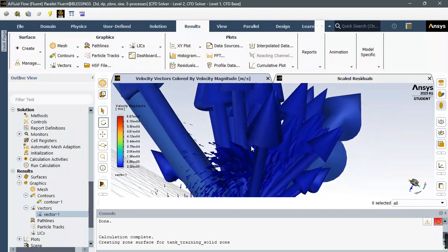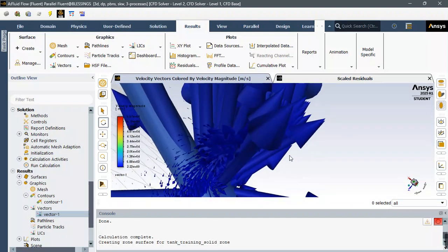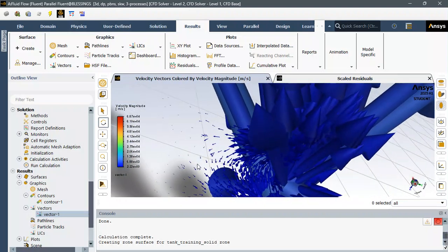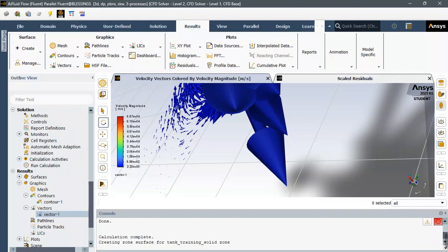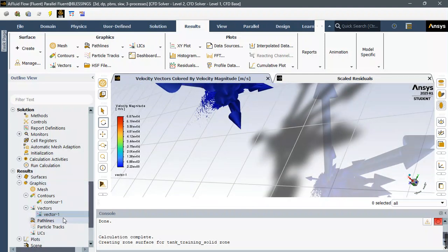You see how they are moving, so you can tell, okay, the particles are moving this way, meaning they will hit the wall. Where we are having a circular motion here, you advise your team to say, okay, if we pick this injector, we'll have particles moving in this fashion. So make sure you know how to consider the walls. For example, at the walls you have higher velocities circulating, moving in a circular pattern. All that has to give you some meaning to say, oh, here we have the highest concentration of velocity. So that's how you can visualize.